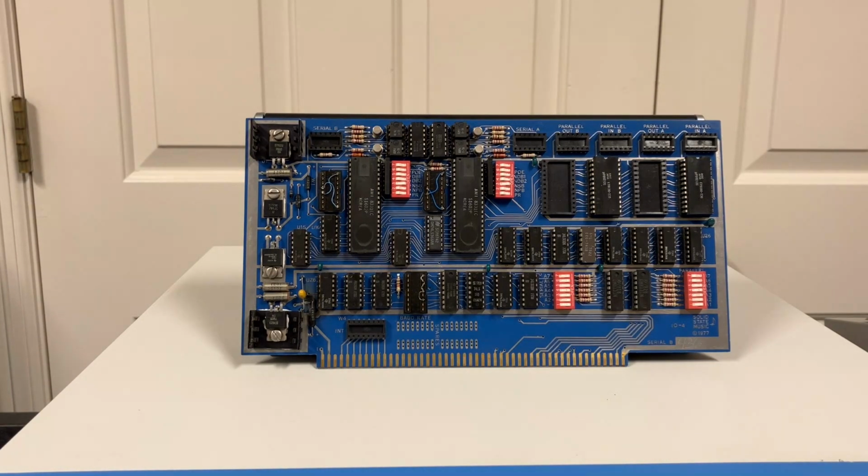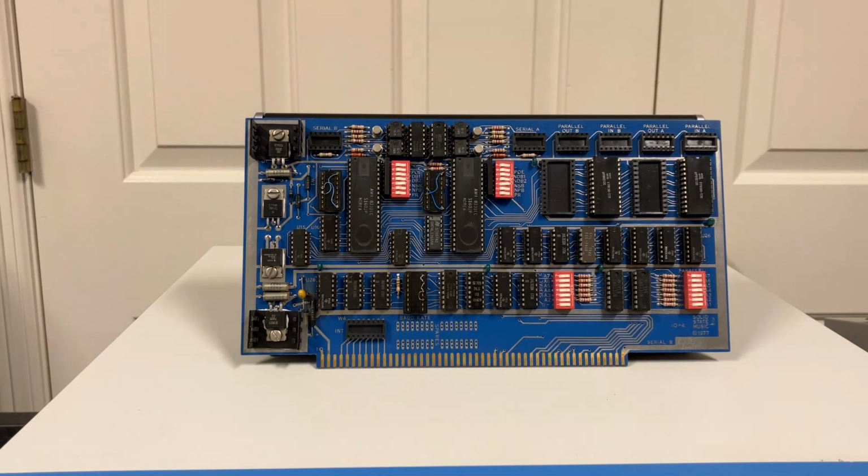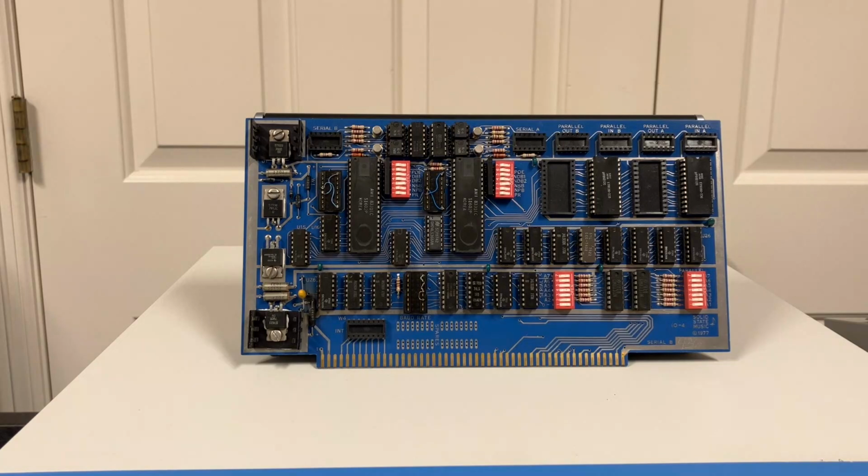Now, any serial interface board that you choose for this project is going to have to look exactly the same as the serial board that was used in the original Altair Cassette Interface. That's an 88-SIO. The board you're looking at here is the board we used in that last video. It's a Solid State Music IO4 board, and it was not hard to configure to look exactly like the cassette interface serial board. However, there are not a lot of boards that can do that. There are some restrictions. Specifically, it's going to have to use the same UART that was used on that SIO board of the cassette interface. We'll touch again on that in just a minute.